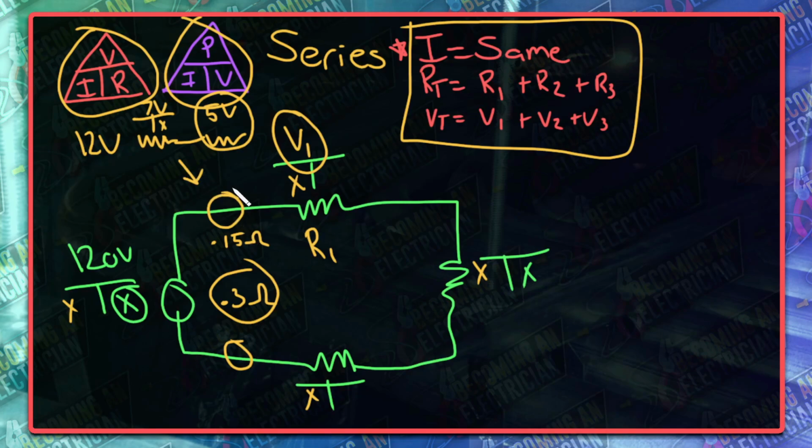You can lower the resistance by running a larger wire size, but in the real world, we really don't look at that too much. That's more about the engineer, or if we're in a situation where you're running the main feed to the home, that's where you'd be looking at voltage drop, okay? Not so much in the home, unless it's a very, very long run within the home. Let's say you have a custom home. Instead of running a number 14, you might say, hey, just run a number 12 to that, even though it needs only 15 amps. We're just going to do it for upsizing the wire, okay?